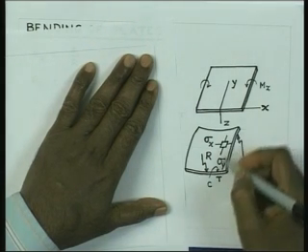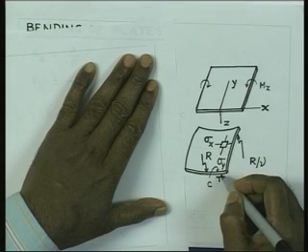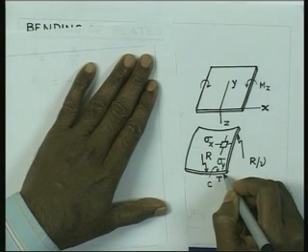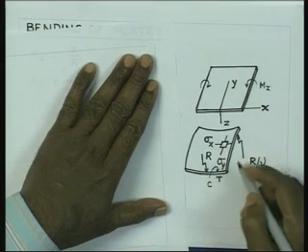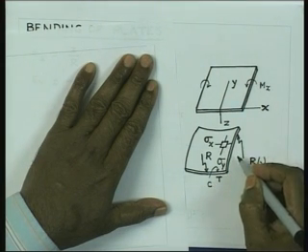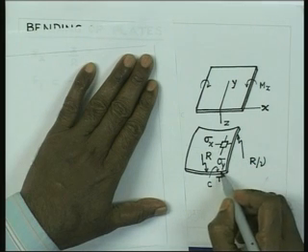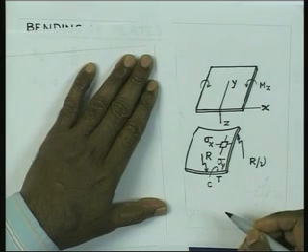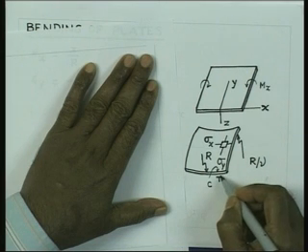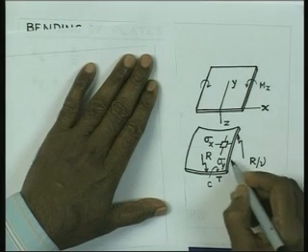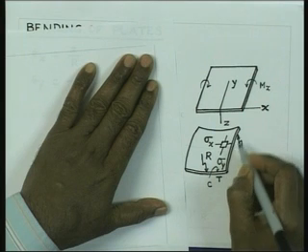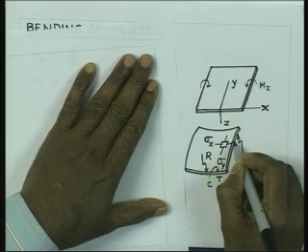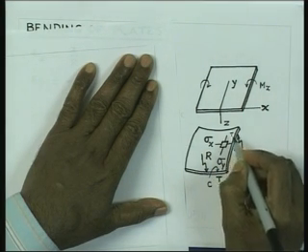When the plate dimension here is substantial, what you find is that when it is trying to get stretched at the bottom fiber, in the direction perpendicular, in this direction there will be contraction, and since there is compressive stress at the top fiber, in this direction there will be extension at the top. So, therefore, you get contraction at the bottom fiber here in this direction, and the top fiber is going to get stretched.